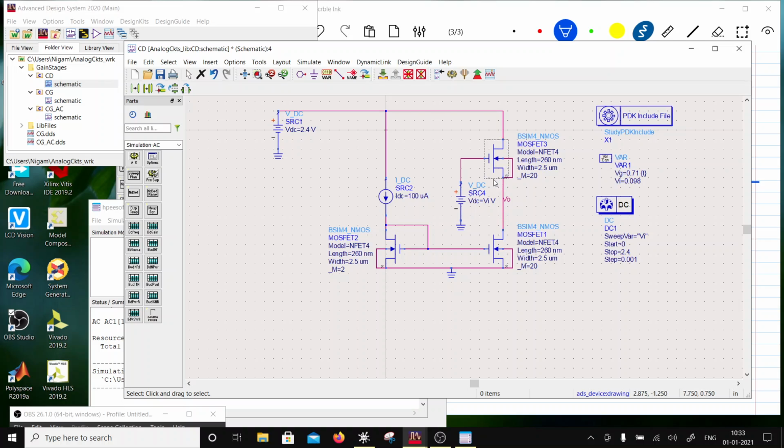It is also known as a source follower. What's going to happen is VO is bootstrapped to VI, and VO is VI minus V overdrive minus VT, right? So if I have a signal on the gate, the signal at the source is going to be the same. It's just that it will be DC shifted. So that's why it is also called a level shifter, or a source follower.